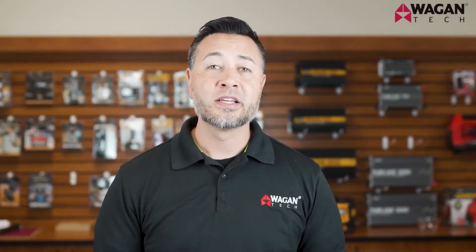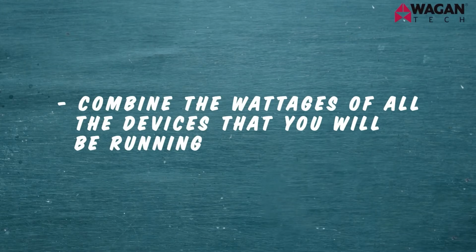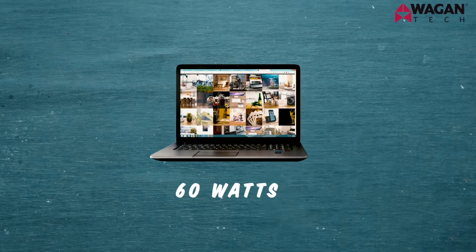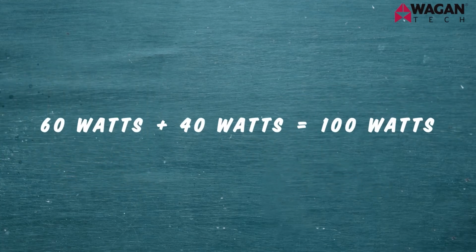Another thing you don't want to neglect is the amount of appliances you're going to run at one time. Just because your lamp requires 60 watts doesn't mean you shouldn't include the other devices in the calculation. So if you're running two devices at the same time, make sure you calculate both of those devices' wattages up in order to make sure you get the correct power inverter. For example, you have a laptop that's 60 watts, and let's say you have a portable DVD player that's 40 watts. You'll add those two wattages up, 60 and 40, and you'll come up with 100 watts.